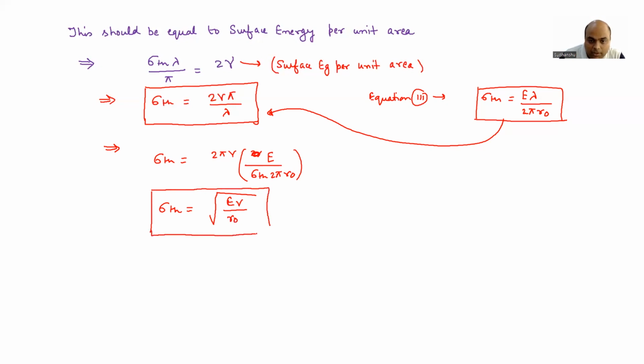So we have got another term related to the theoretical strength, but this is based on the energy consideration. Okay, so what you see here is E, R naught. Now you know that is the equilibrium distance between the two atoms, no forces there. And gamma is the surface energy of that particular material. Okay, so we have now got two equations. One we derived before and one just now with respect to the surface energy.